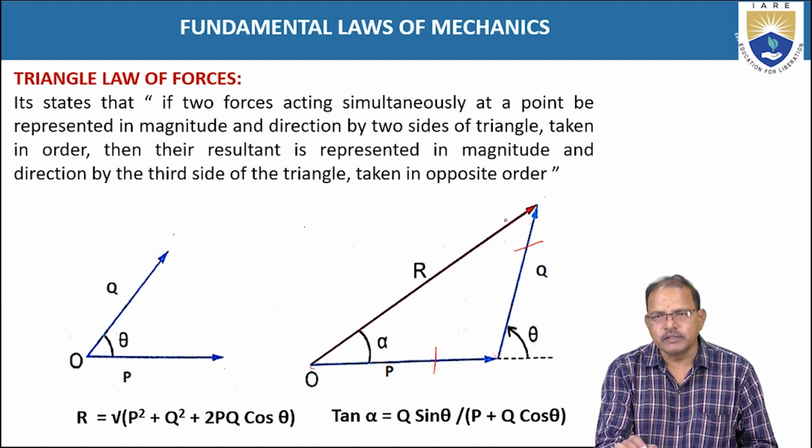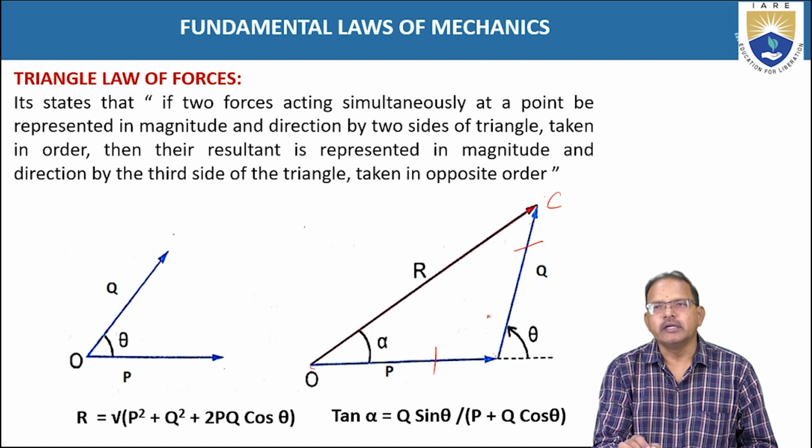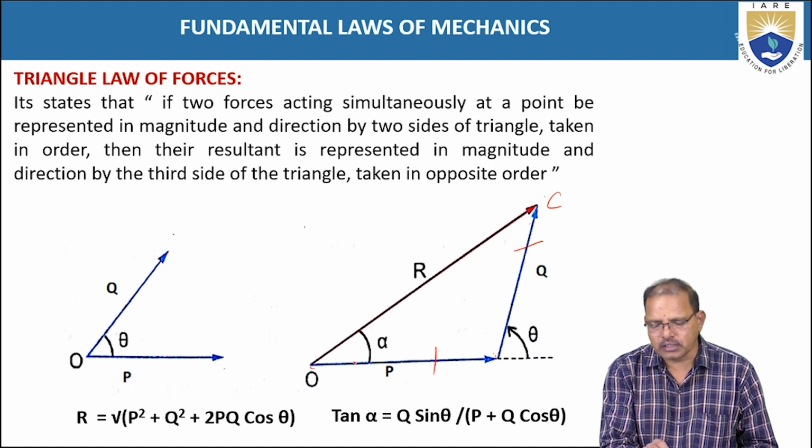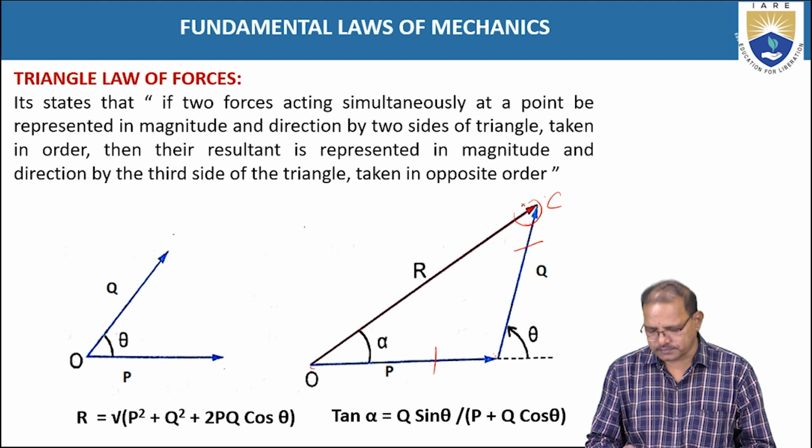Then the closing side of the triangle, that is here OC, is representing the resultant of these two forces, and it is represented as R, but in opposite direction. That means one direction is there, and here it is in the opposite direction.